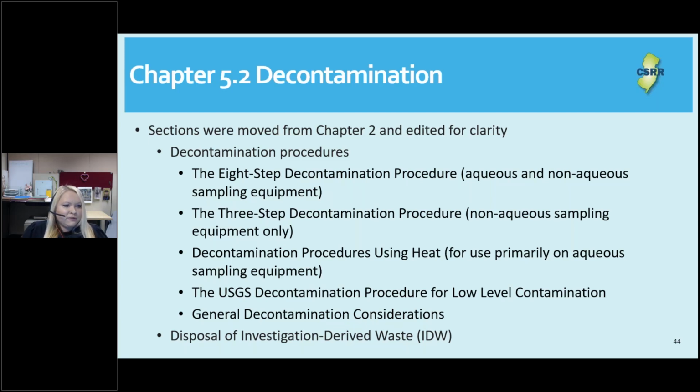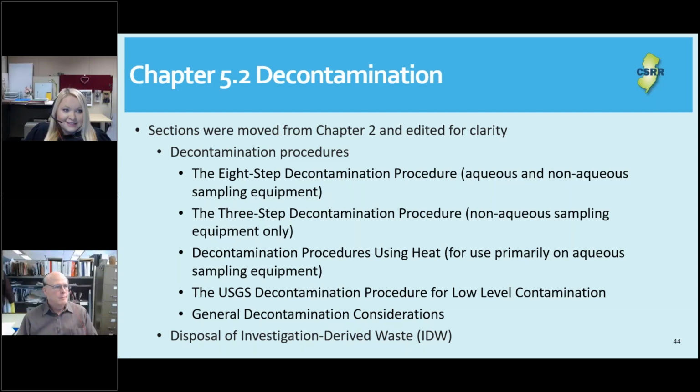For decontamination procedures, in most instances, fixed laboratory decontamination is preferred to field decontamination, but options exist for field decontamination for everything except balers. Decontamination is an important aspect of quality control. Improperly cleaned and prepared sampling equipment can lead to misinterpretation of environmental data due to interference caused by cross-contamination.